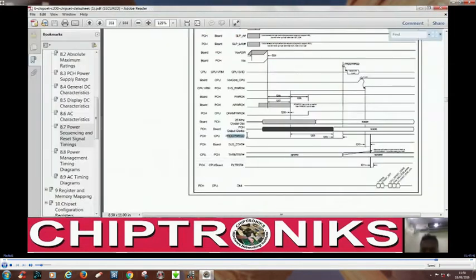And this happens when the clock has been generated, right? So at this point of time, the CPU has got supply, it has got clock, and now it needs reset in order to read data from RAM, in order to start booting from BIOS, right? At this point of time, the CPU has got supply, it has got clock, and now it needs reset.